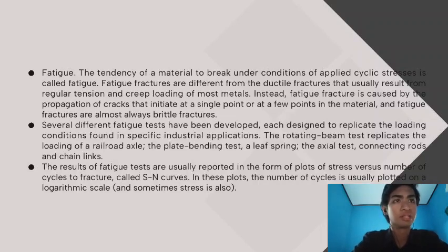The plate bending test, a leaf spring; the axial test, connecting rods and chain links. Some tests run under constant load, while others run under constant strain. Therefore, tabular values of fatigue strength or fatigue limits are of value mainly in material selection, rather than useful in actual design calculation.